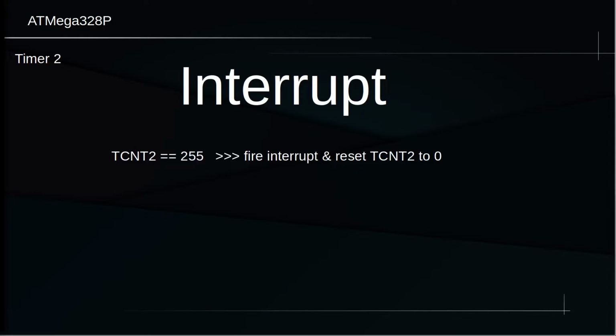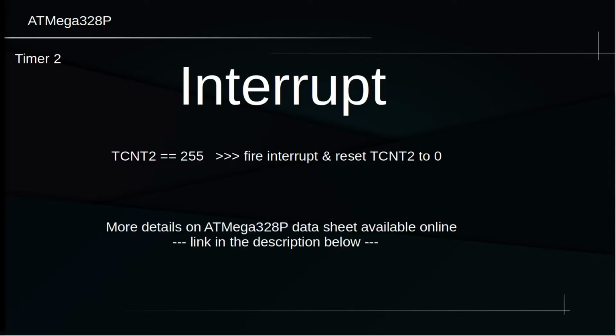So at this point I will stop here, since I have described the details that we need. But if you want to know more, the best way to learn is to get a copy of the ATMega328 datasheet and look for the section about timers. It is a large document, 294 pages long. Let's take a look at the code I wrote to handle the voltage reads at the potentiometer using timer T2.